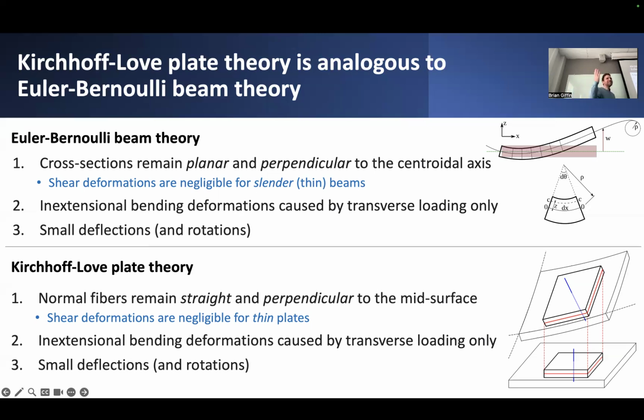But not all plates and not all beams are necessarily thin. In some cases, you might have beams or plates that can't quite fit into exactly these idealizations, where the depth of the beam, maybe it's somewhat slender, but if it becomes sufficiently thick or deep, at a certain point, shear deformations are no longer strictly negligible. And this particular assumption, that the shear deformations are negligible, goes away. It's not really appropriate to consider that anymore for relatively thick beams.